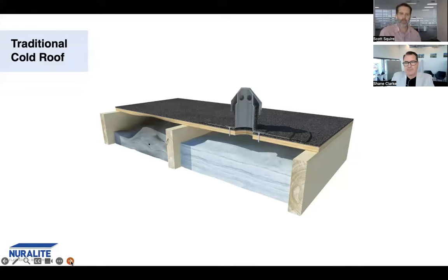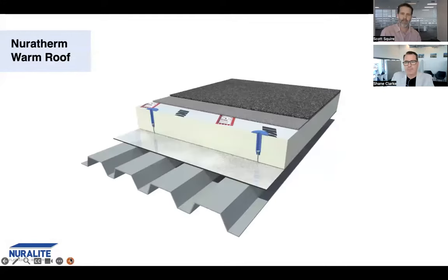But the example that I mentioned, the owner, the architect, ended up adopting a warm roof system on a metal tray, which, Jade, if you can just flick to that next render. So that's essentially what was adopted. Now, the benefit of the metal tray over the plywood is that you don't need supporting structure at 600 mil centres. In fact, the purlins for that metal tray could be set at up to 2.7 metres internal span. End spans are less, you're looking at about 1.8 metres.